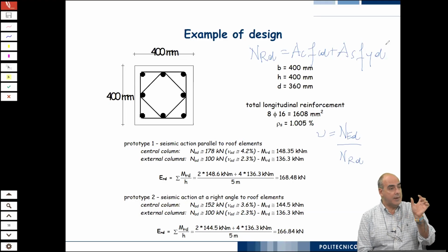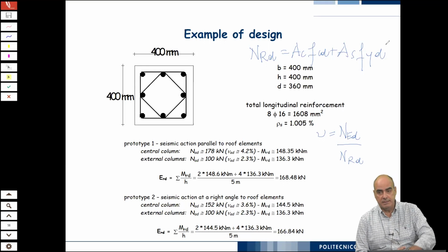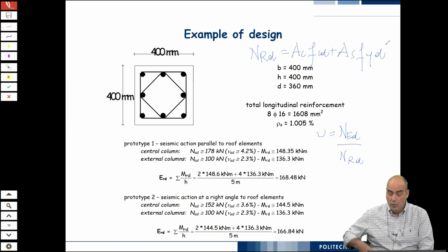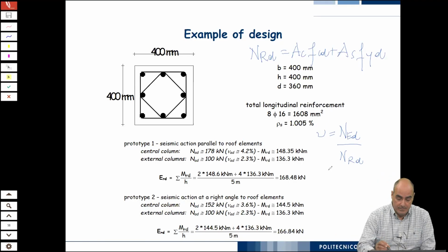So you see, we are at the limit of the serviceability limit state for the service earthquake, for the earthquake design. But we have plenty of margin for the axial capacity because we are just engaging it a few percent. What does it also mean?